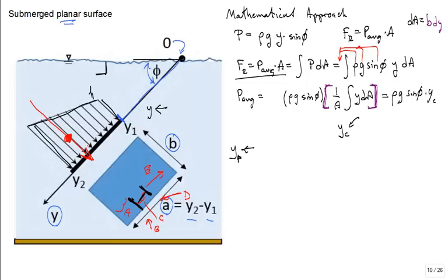Okay? So if I'm going to do it mathematically brute force, how am I going to solve for y sub p? Sum of moments equal to 0. Good starting point. Sum of moments about the point O. What does that mean? Let's start around this point right here, O. So the distributed load has to have the same equivalent moment as the resultant force where it's placed. So the resultant force, F of R, needs to be replaced at y sub p.